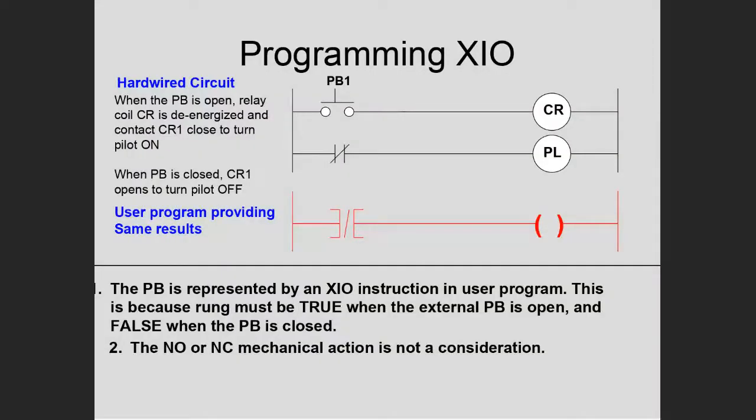Okay. So now, if you understand what I just said, you got the push button, it's open. So if this is open, that means no power is getting to that contact. That means that the relay's off, so that armature is touching that top contact I just showed you on the whiteboard. It's touching the normally closed contact. And if you were to push this button, that would turn the relay on, and the magnet will pull it down and disconnect it from the circuit. It'll go down to the normally open contact, and it'll close it.